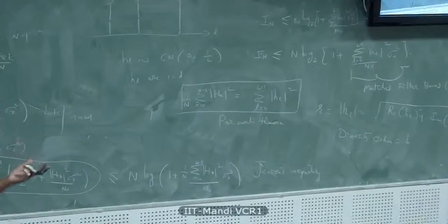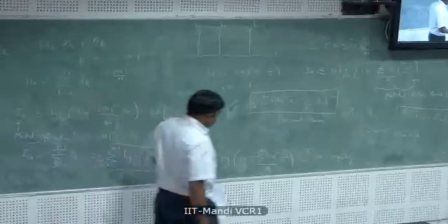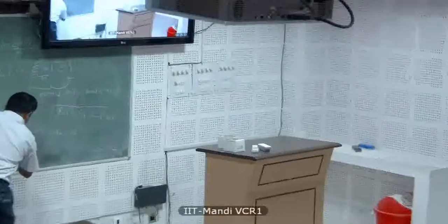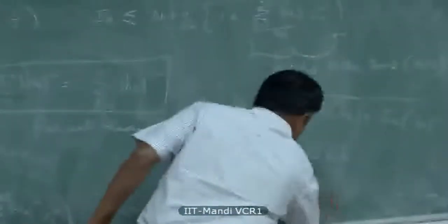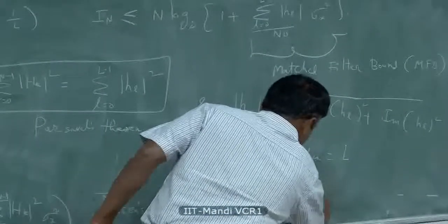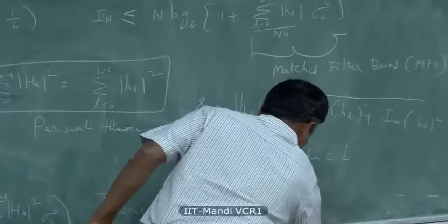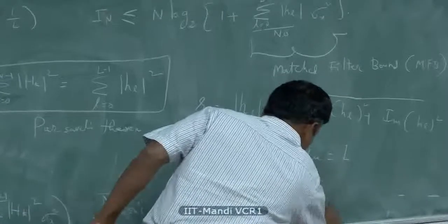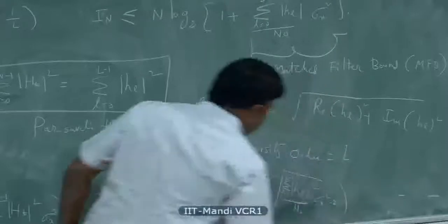And if you calculate the probability of error for, let's say, an uncoded system with BPSK transmission, the average probability of error can be expressed as this, and maybe a factor 2 is here, since it is binary.